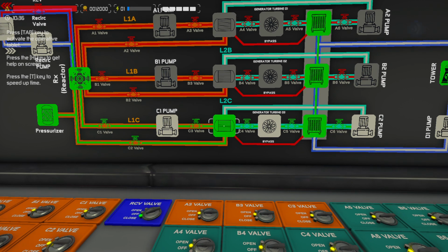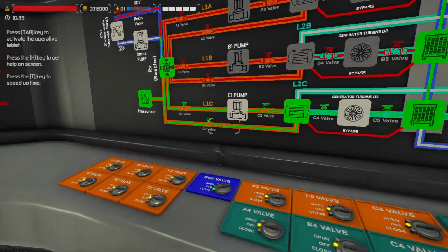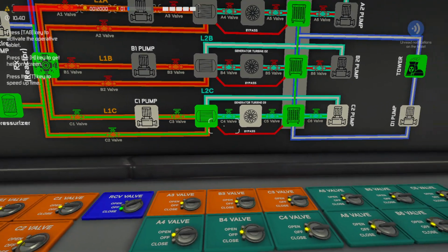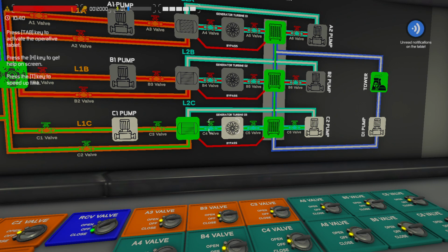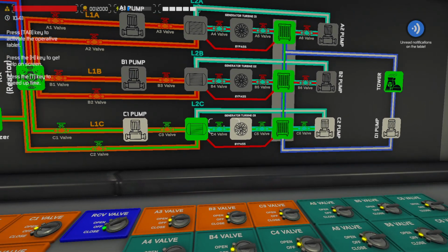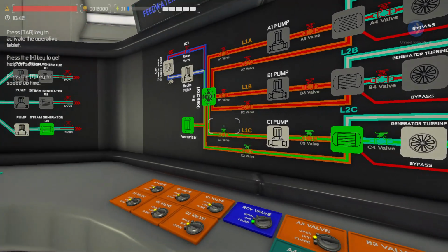It goes through another tube, and those tubes heat up, and then the steam generator water touches those tubes, and the heat transfer occurs and makes steam, because this is at a lower pressure than your reactor, because it's open basically to atmosphere. I mean, it's not at atmosphere, but the pressure in the steam generator is significantly lower than your reactor, and you can see that while you're operating.